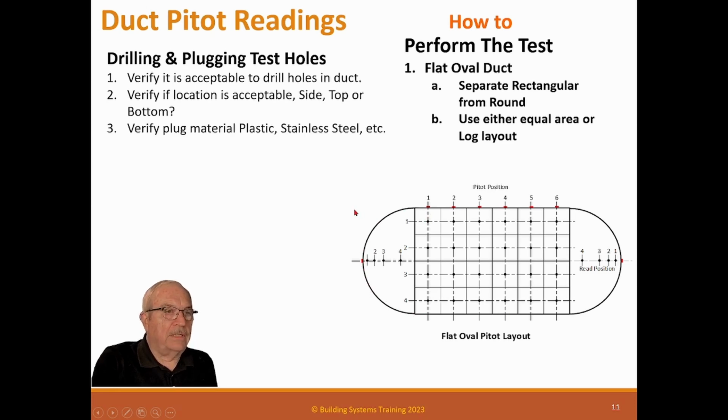You need to look at the type of duct. What material is this duct? Is this duct just galvanized sheet metal? Then the plastic ones are probably fine. Are they outside? The plastic ones may not be fine because the sun may eat them up. Or if you're in a stainless steel duct, plastic ones are probably not going to be fine. There's a reason the duct's stainless steel, and it will probably need some kind of stainless steel plugs.